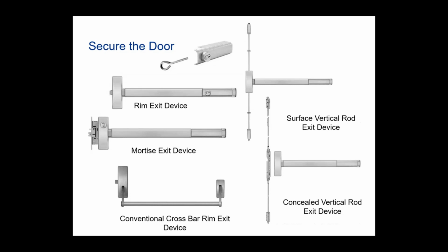You're hardly ever going to see the crossbar anymore because they no longer meet certain codes and standards in our industry. They have the ability to allow a person to chain the opening down, and that does not meet life safety or NFPA. So this little fire guy here shows you that these are rateable, fire rated, but I would strongly recommend against the crossbar rim exit device.